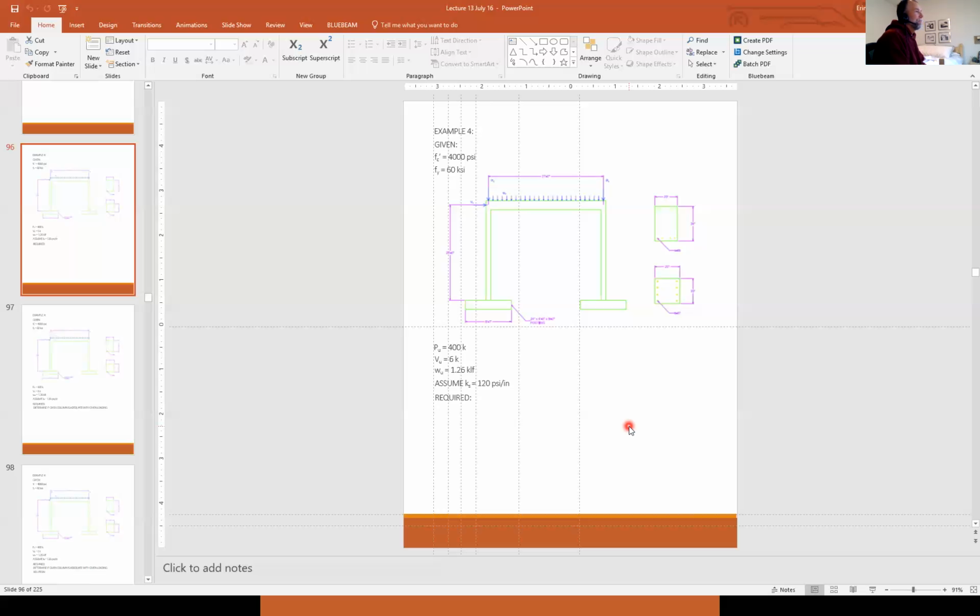And what I mean by fair is that if I didn't cover something very clearly, and everybody in the class except for maybe a few missed it, like that d from the top of the beam to the lowest layer of the steel is d sub t, but d to the center of all the steel is d, and those are different, and that wasn't really clear.